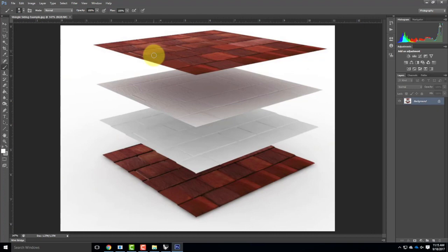Plus they have some grain that's on the wood itself. So in Rhino, we could make these triangles and then glue the triangles together, and we could render it. But it seems like an awful lot of work to go all the way around your building. So instead, we can actually do two different things to the material. We can apply a little bit of grain for the wood. That's called a bump map. And then we can apply a second one, which is called a displacement map.